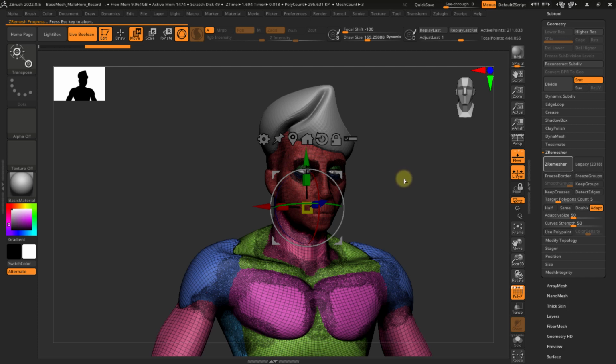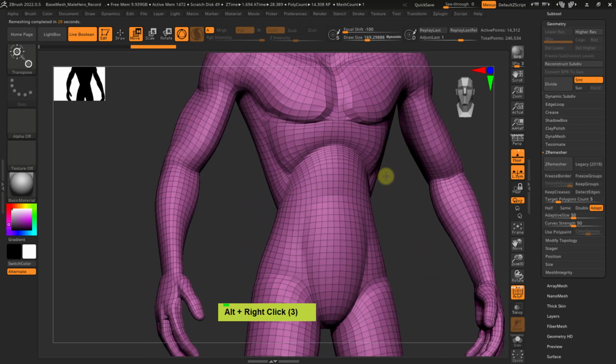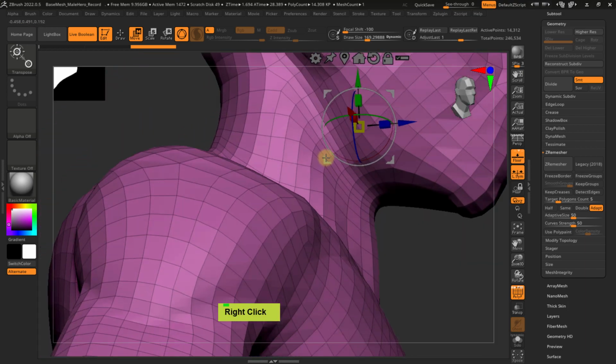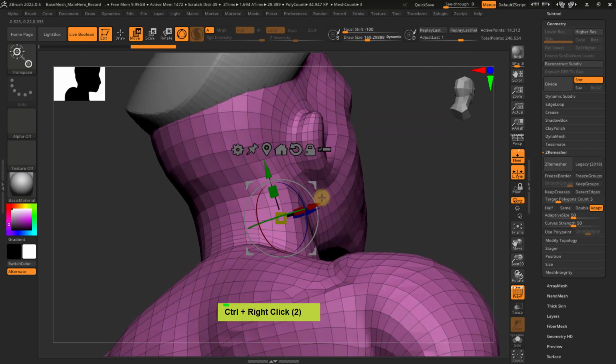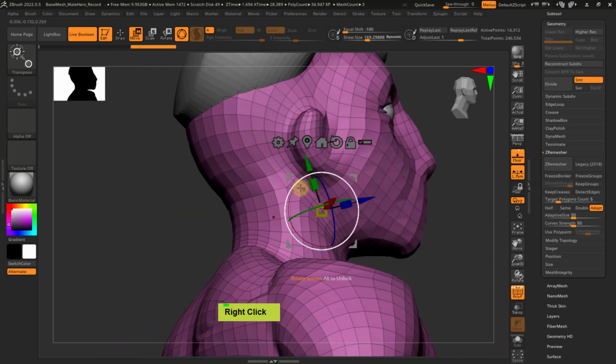Basically, it's looking at the original shapes and trying to maintain an edge flow. So it is pretty smart, and this is one of the features that made ZBrush big, because in just a couple of minutes you have this remesh, and then you can work on it. And here's the deal. Can you see why we have smoothed out this area? We have smoothed out the chin area, and where we have the smooth parts, this transition, the polygons will become much bigger, much more fluent. The edge flow is much better.